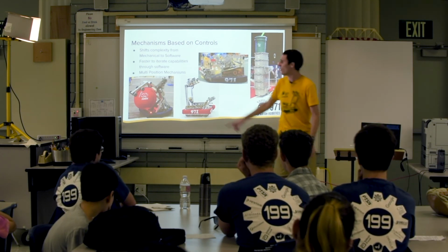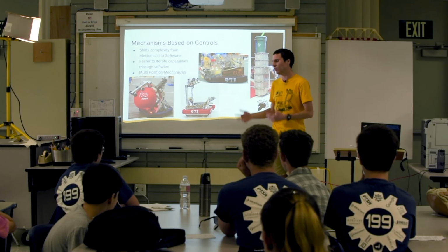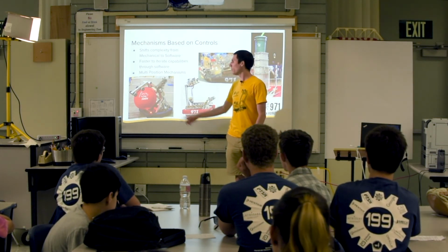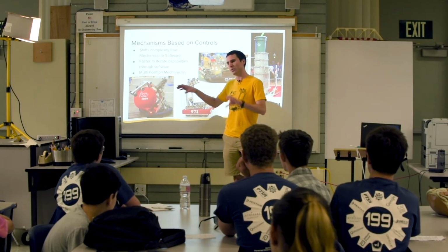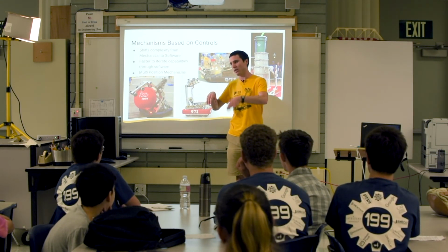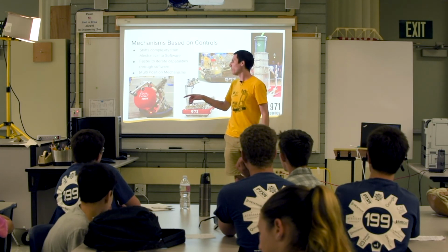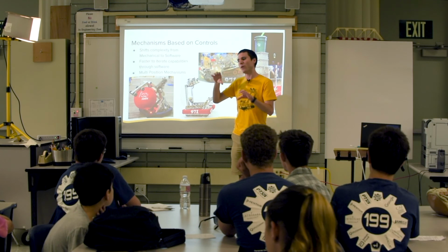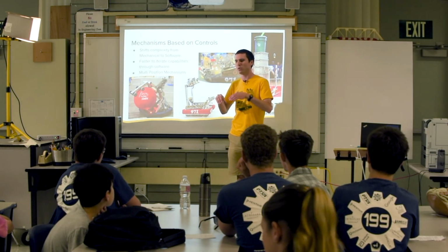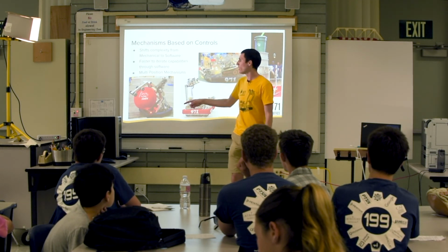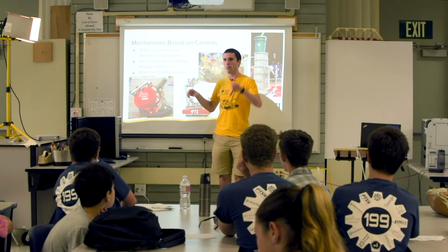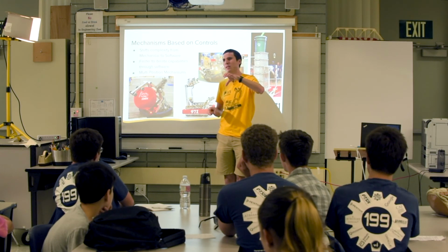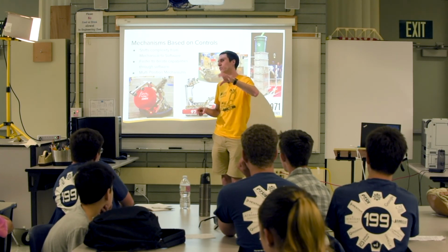And then one of my favorite applications of controls leading to good robot design is our 2014 robot. Here we knew we wanted to be able to intake the ball, so we wanted to have a claw that we could move up and down. And then we also wanted to be able to clamp on and unclamp the ball so that we could grab it for intaking, and when we were shooting, we thought we wanted to open up a little bit. So we could have designed that with just one claw that went up and down, and then it had a piston or something that would open the top part of the jaw just a little bit.